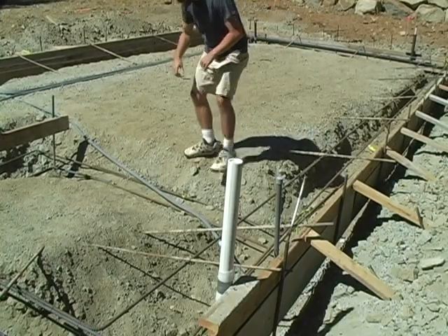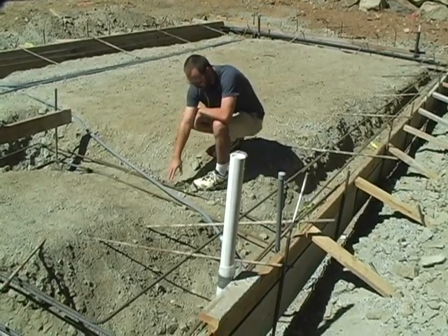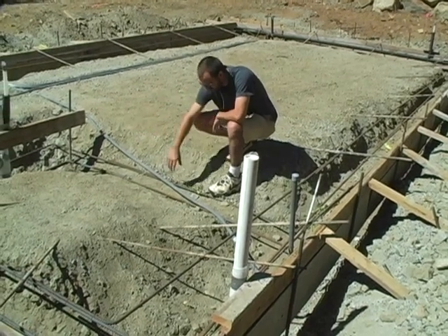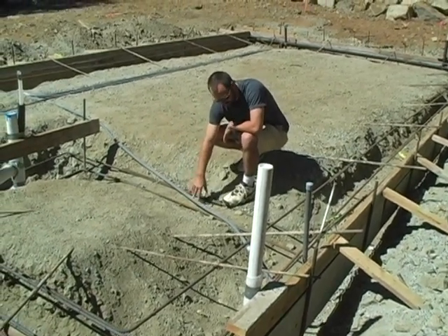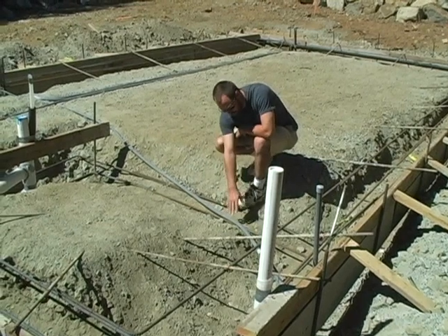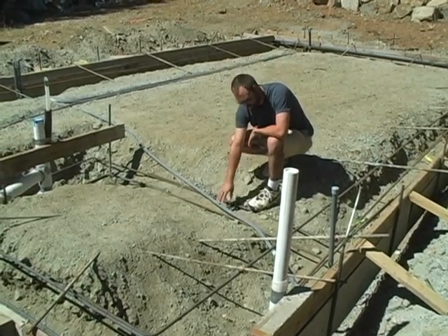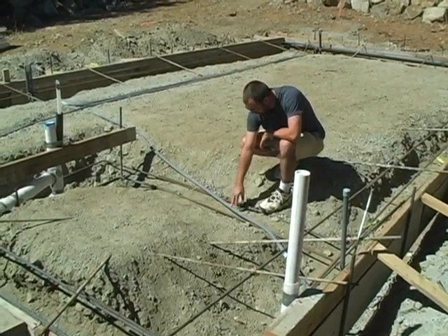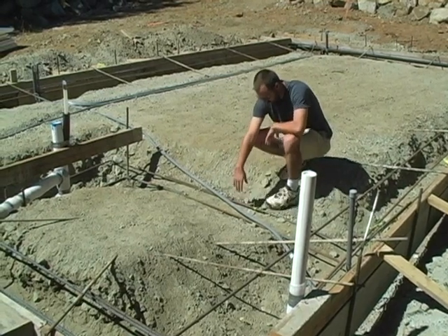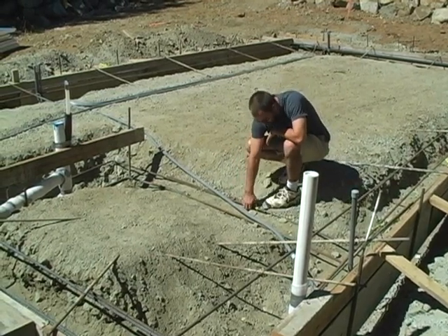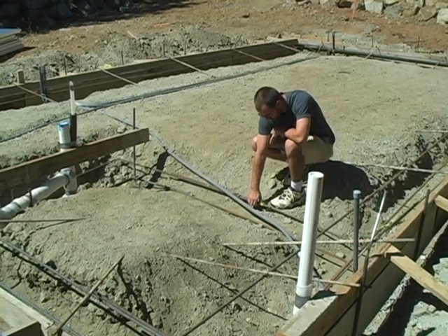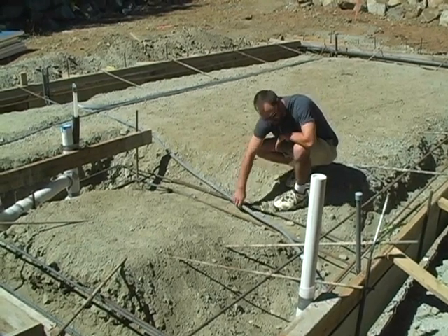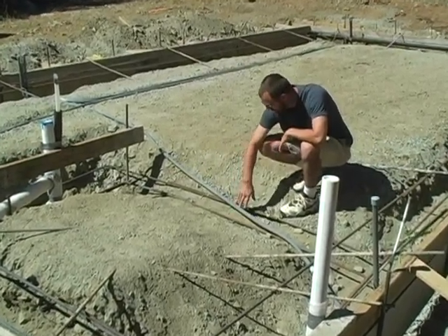So you can see here in the bottom of this interior wall footing, we have a structural wall that lays in the middle here, so we have to have a bearing footing underneath it. We've run the conduit for the home run back to the electrical panel, and in this case it's just on top of the rebar that's going to be set up in the footing. Now we'll actually pull this rebar up when we pour, get it up off the ground, so there's enough flexibility in this pipe to allow us to do that.